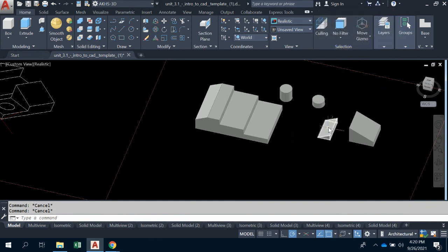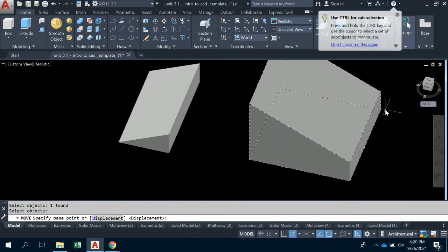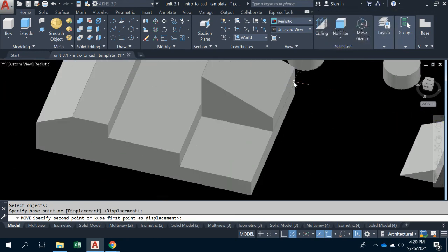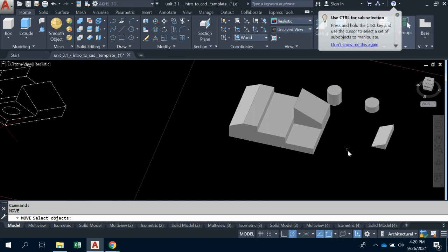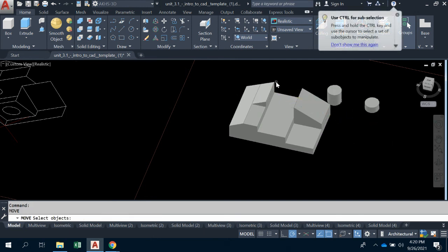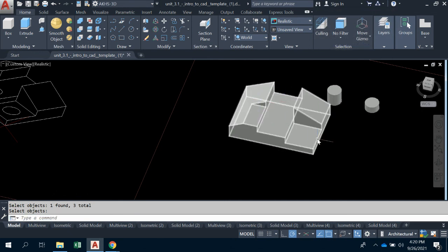Now I'm going to move these two in place, and then we'll save these two for last. So first, I'm going to take this corner and go to this corner. So move this, paying close attention to what you're selecting. So this corner to this corner. And then we'll take this corner and go back here. That way you don't have to move anything around, rotating wise, before you place it like that. You can go ahead and union it. We won't have to union after this point anyway. So now it's one solid piece.